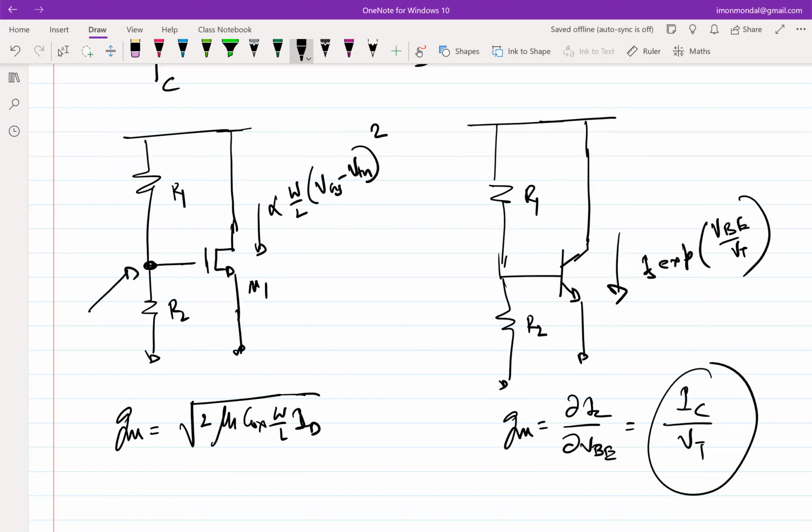No, you use MOS for both digital and analog, but I'm distinguishing between IC design and discrete level design. When you are doing designs on boards, like breadboards, the size of the component matters, right? So you don't want to put 10 components just because you want 10 times the GM. Board size also matters, so it becomes difficult.